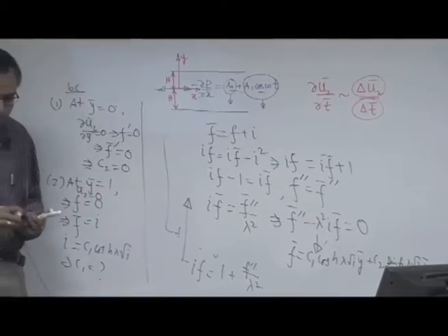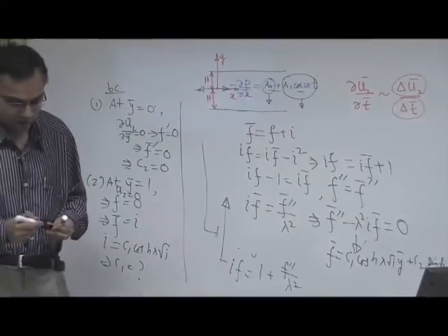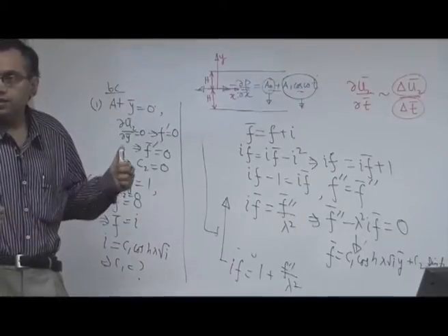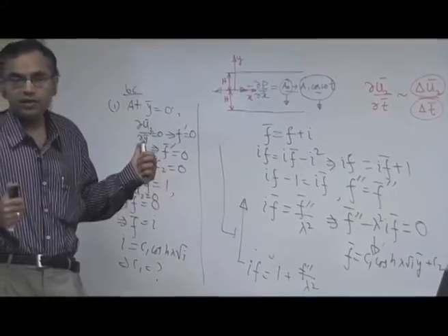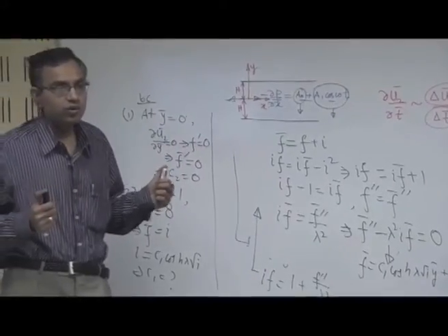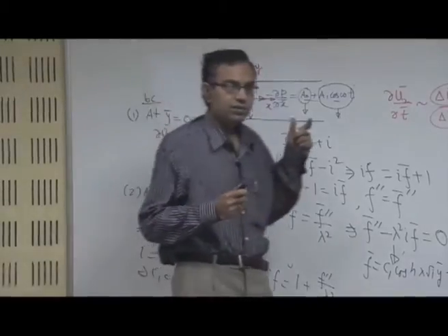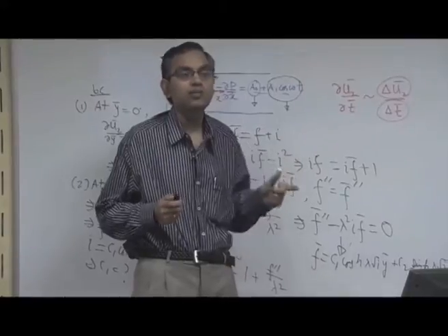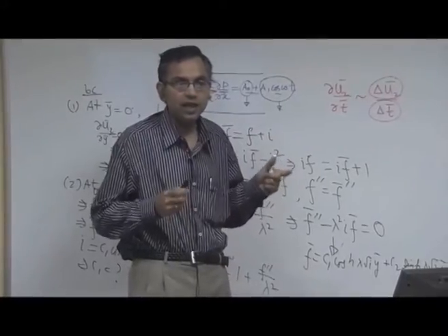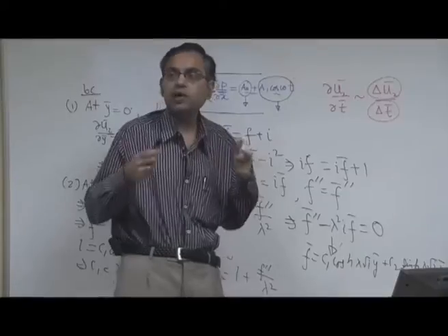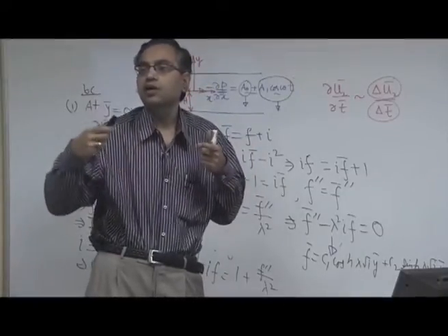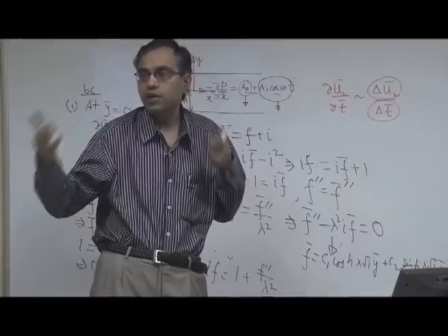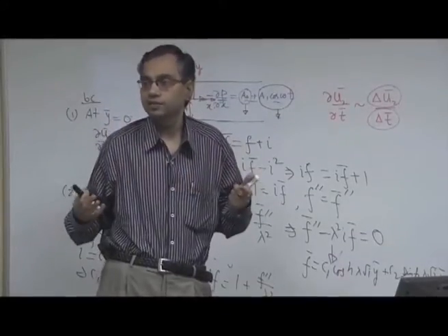So, I will utilize the slides to sum up the solutions for the Stokes second problem and this particular problem. I will advise you to plot the Stokes second problem solution as compared to this problem for different values of lambda, and see for which values of lambda this problem essentially boils down to a problem with a solution similar to the Stokes second problem, and for what values of lambda it does not.